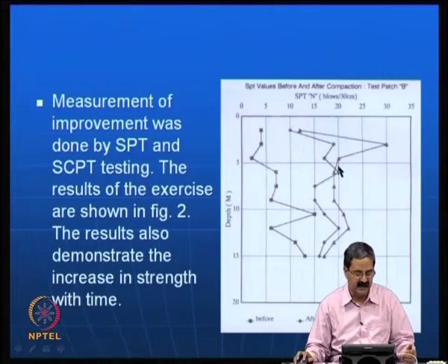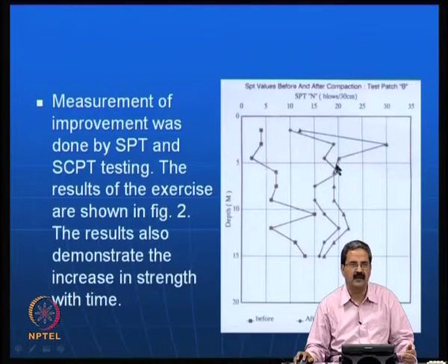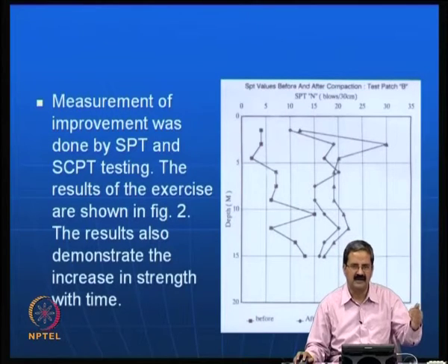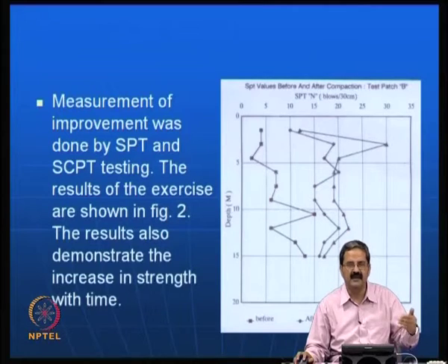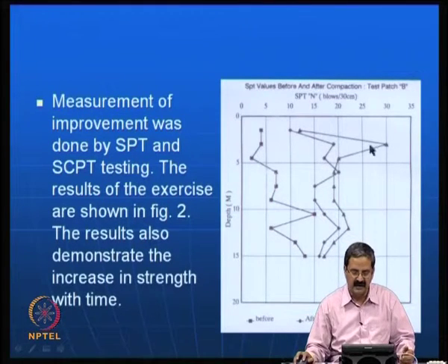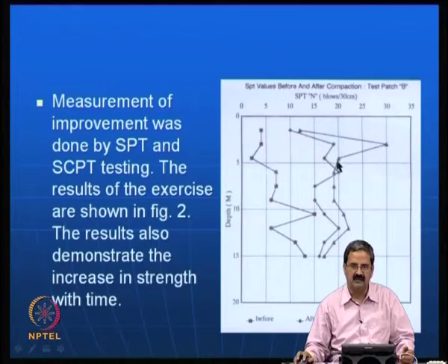What it means is that the time dependent behavior is there. If you allow things to happen, for example consolidation is a time dependent phenomenon in clays. Even in sands, because of the pore pressure dissipation, in about 15 days to 1 month there was an increase in strength which was observed, which is good. So